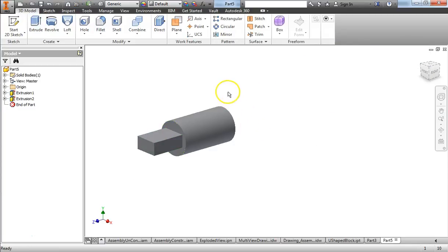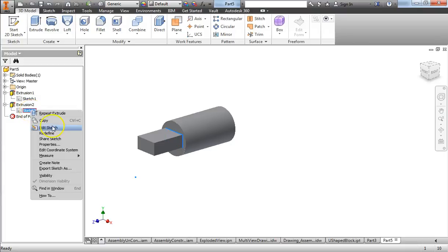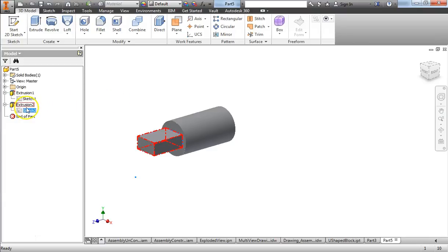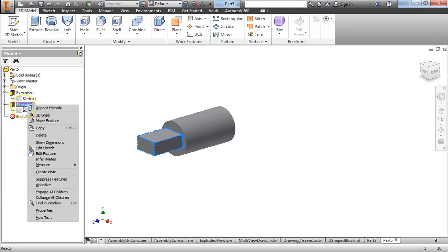Okay, so there is a quick introduction to the sketch-based modeling Inventor runs for us. All the 3D modeling really is based on two-dimensional sketches, and those sketches can be updated. You can find them in the browser after you've used them to create any 3D parts by finding them and right-clicking on Edit Sketch. You can also get to them by right-clicking on the 3D modeling tool, in which case you can edit the sketch or edit the feature. That would be editing the extrusion.